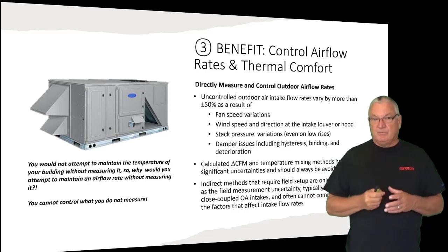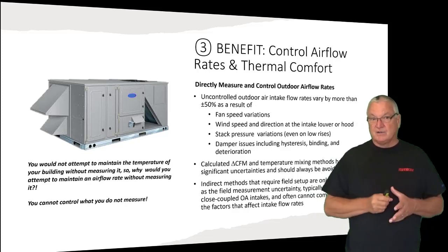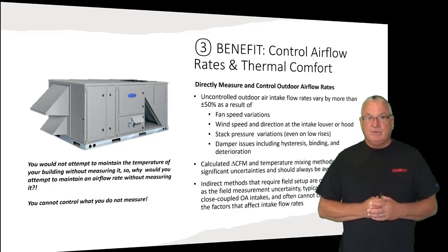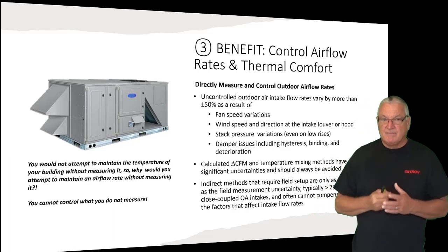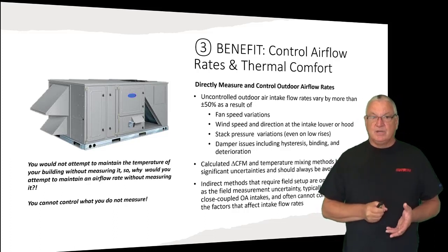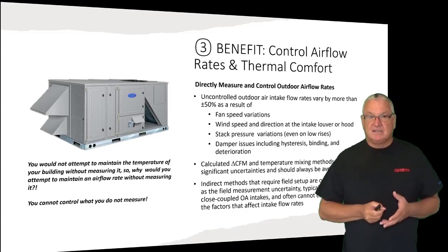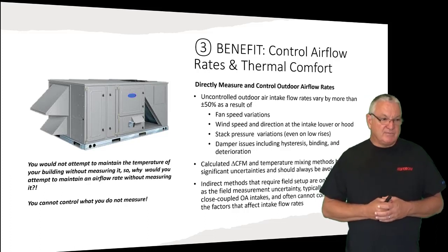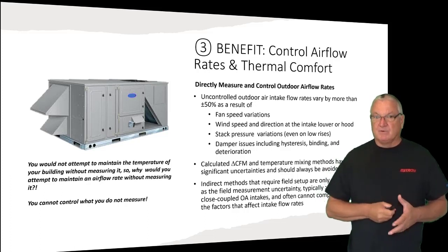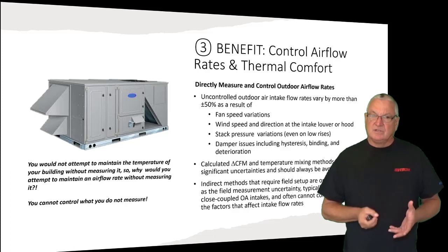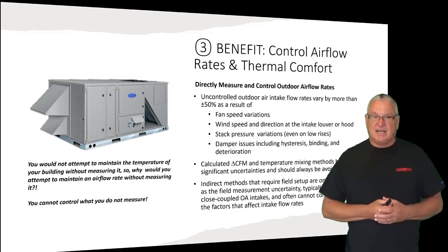Either way, we really believe that it's not just monitor for monitoring, it's monitoring for control. And we would show you that direct measurement really is a superior way to do it. There are some calculated methods that folks use from time to time, like delta CFM or temperature mixing. They don't really work. I'd like to be able to demonstrate that to you.